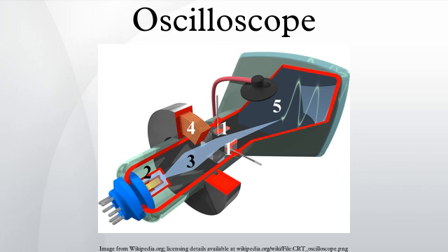Automatic sweep mode. Triggered sweeps can display a blank screen if there are no triggers. To avoid this, these sweeps include a timing circuit that generates free-running triggers so a trace is always visible. Once triggers arrive, the timer stops providing pseudo-triggers. Automatic sweep mode can be deselected when observing low repetition rates.